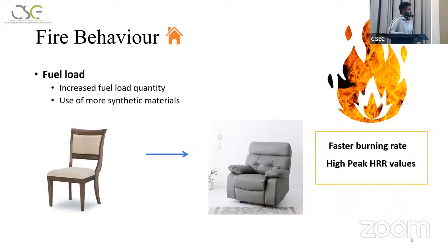Because of this conversion of construction materials, the modern construction materials and the furniture can have a high fuel load, and these are synthetic materials, so they can ignite very fast and release high peak heat release rates.